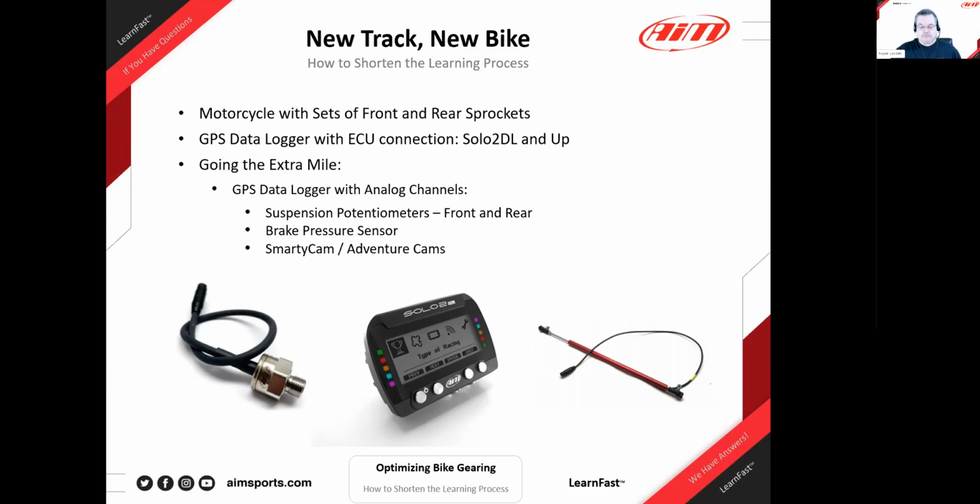This is just a general list of things that you should probably have in a box with you when you're going to a new track, especially if you want to race or if you're chasing time. As far as the topic of this webinar, it's really good to have a set of front and rear sprockets, usually four different size rear sprockets and two sizes of front sprocket. As far as data analysis, you can do a lot with a Solo 2, and we've already talked about that in previous webinars. But for gearing optimization, you do want to have a Solo 2 DL because you want to be able to log RPM.